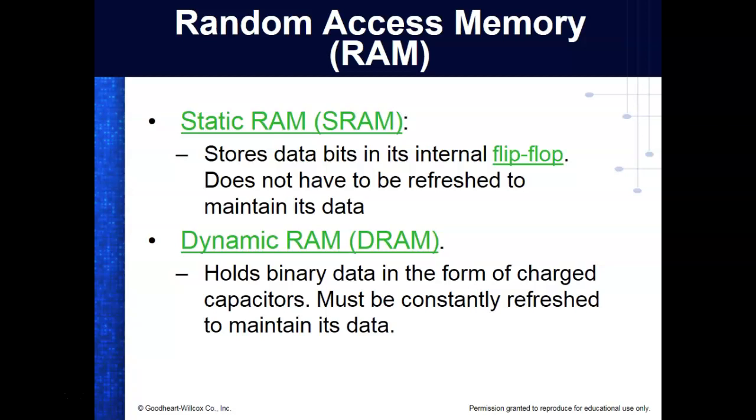Somebody says I've got 8 gigabytes of memory. It's usually dynamic memory. And what this does, it uses a little device called a capacitor to store bits, 1s and 0s. And it takes 1 transistor per cell. So it means automatically I can get 6 times the storage, DRAM storage, that I can for 1 static cell. So static cells, they don't have to be refreshed. The problem with DRAM is that it acts like a little tiny battery. And what happens to batteries? They discharge, right? So what we have to do with the dynamic memory is we have to refresh it.